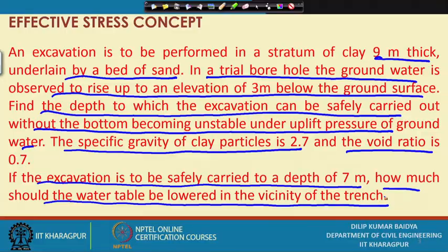So, there is a 9 meter thick clay layer, below that there is sand, and the sand layer is under pressure. How much pressure? When we make a borehole, we will see how high the water has risen. The water table is actually shown 3 meter below the ground. While excavating through the clay layer, which seems highly impermeable, it is not showing the water table, but when you puncture it, go to the sand and make a borehole, we will see the water table up to 3 meter below the ground surface.